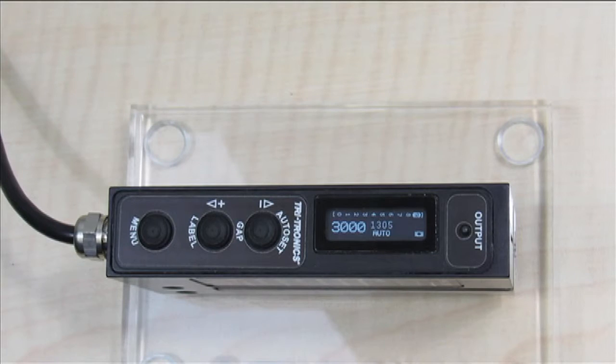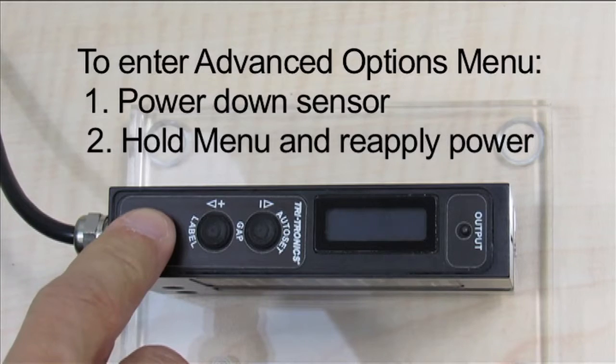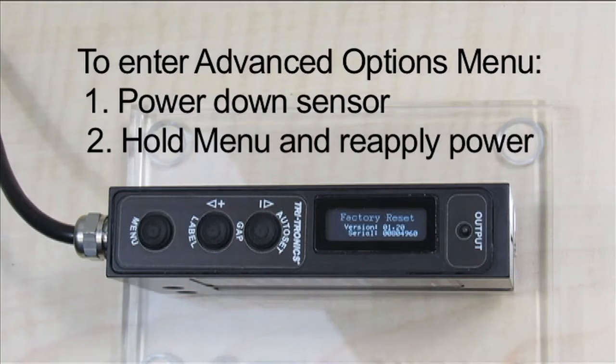To enter the Advanced Options menu, first power down the sensor. Then reapply power to the sensor while holding down the menu button for 3 seconds, until you see Factory Reset displayed on the screen. You are now in the Advanced Options menu.